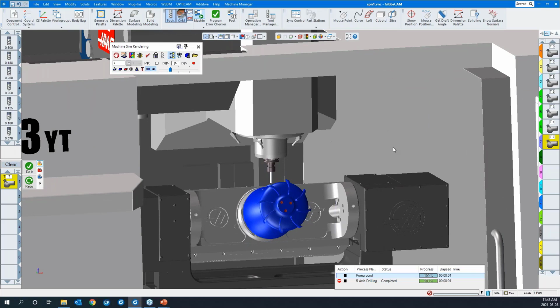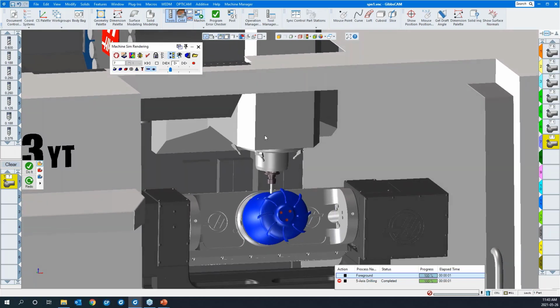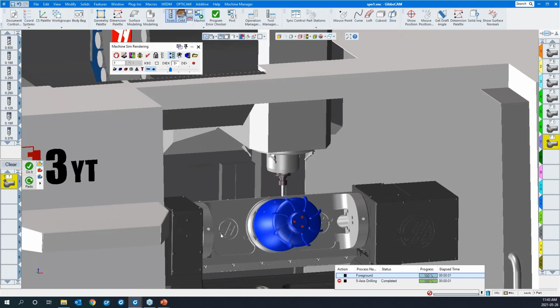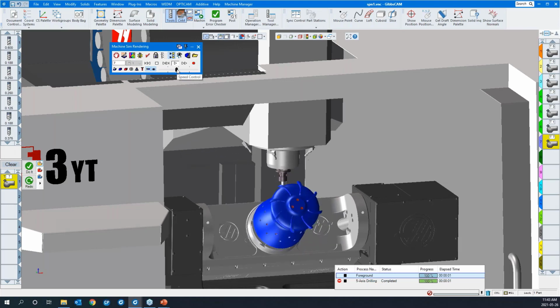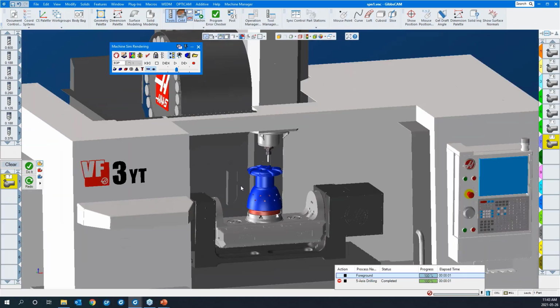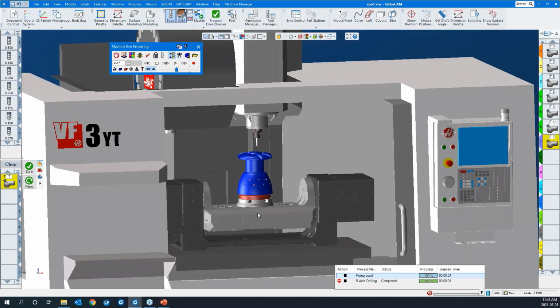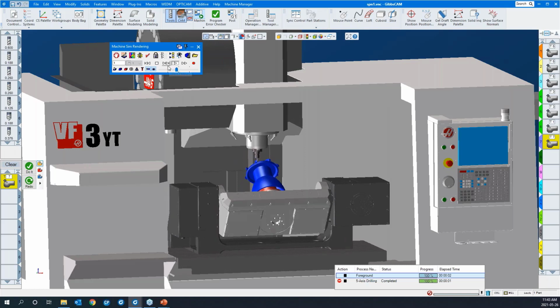Okay, so that collision checking we were talking about in OpSim is also available here, except it's checking much, much more. It checks the spindle against any component or the coolant nozzles. It checks it all. Like that. If I turn off selected ops, meaning run all of the operations, now I can just let that get going here and you'll see that it pops out. Yeah, like that.